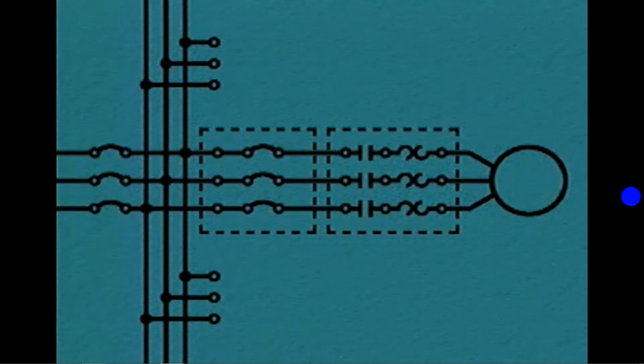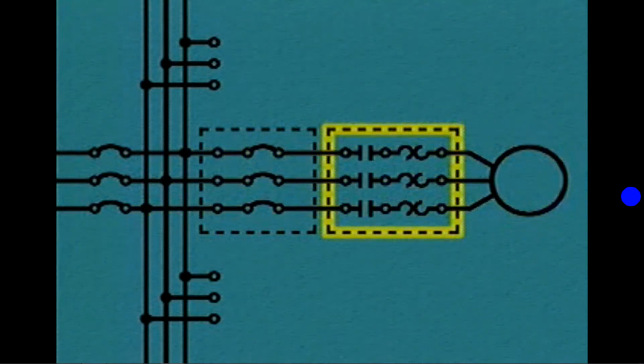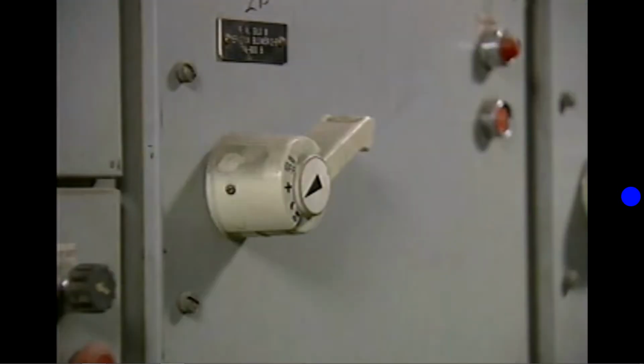An effective way to troubleshoot the motor branch circuit is to start at the electrical middle. This method of dividing a circuit allows about half of the circuit to be eliminated on the first test. In this example, the motor controller is approximately at the electrical middle, so it is a good starting point. The housing of this motor controller also contains the circuit breaker. This arrangement makes troubleshooting more convenient since both parts are located together and are easily accessible.